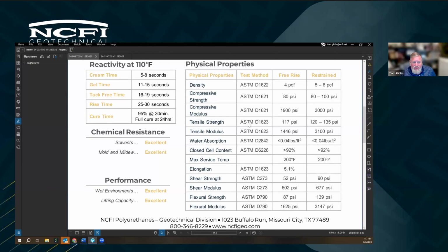I've heard higher numbers depending on the system of exerted force that it's creating. But as far as the proportioner that's pumping this stuff, this is where there's a huge difference in equipment versus cementitious grouting equipment. We don't rely on pump pressure for this. We rely on the expansion of the foam.